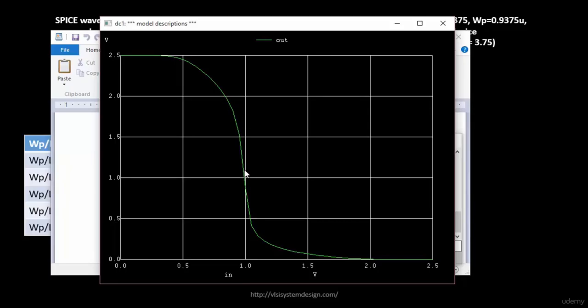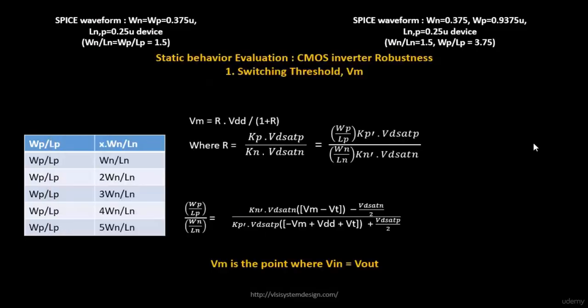That's why at this particular area your VGS is equal to VDS, and your current has an inverse direction. Your IDSP, the drain current of your PMOS, will be in this direction, and the drain current of your NMOS will be in this direction. So if you note the directions of the current at this node, your PMOS current goes this way and your NMOS current goes this way, so the directions of the currents are inverse.